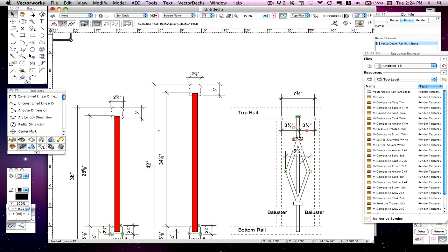So you want to make sure you design or get a center panel that meets this requirement. Then I take these dotted lines, which are the balusters, and I move them in and come to a point where I know this is the clearance I need to place this particular object.